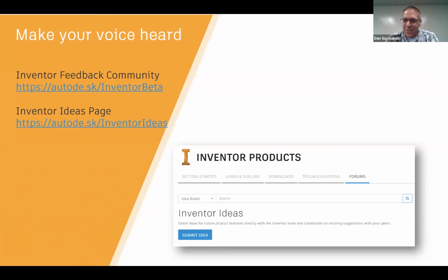There was also a question from Patrick, I believe, on FrameGen. Will we be able to see actual part preview instead of wire preview? I'm currently using Inventor 2018. You'll be very pleased with Inventor 2020. There's a great deal of enhancements to FrameGen, as Garin alluded to, but one of them was introduced in 2019.1, where we took that green preview and made it more of a shaded preview.